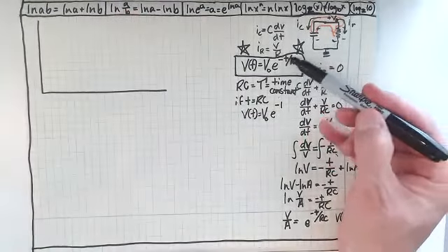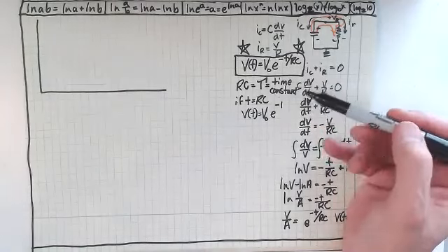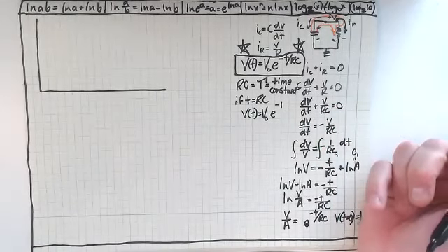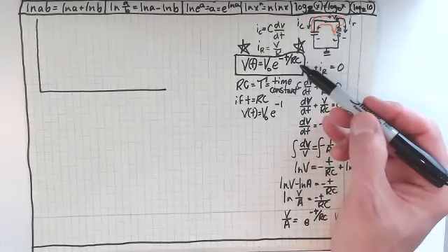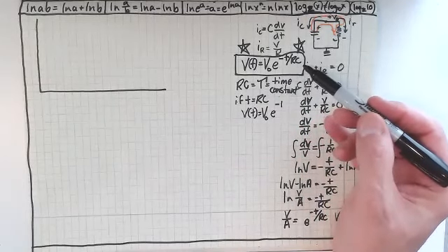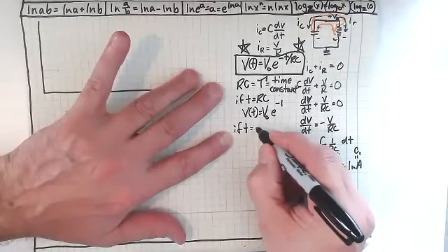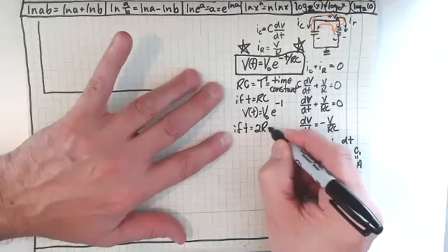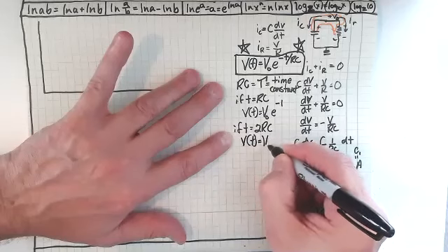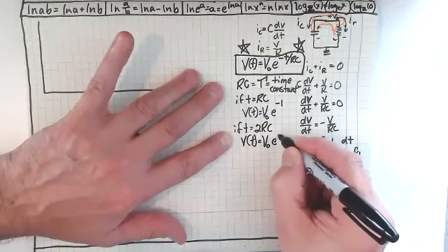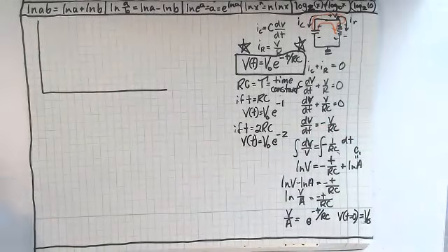Because t and RC are equal, so it would be RC over RC, or t over t, and it would be e to the minus 1. How about if t is twice as great? If t equals 2 RC, then V of t equals V0 e to the minus 2, right? Does everybody see that? See what I'm saying here?